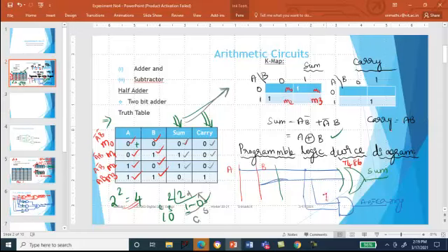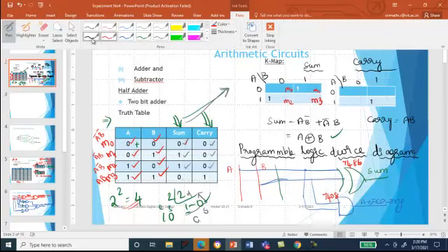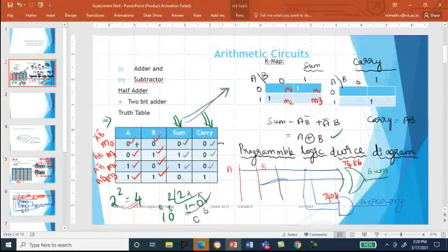So this can be implemented by using the IC 7408. Okay, 7408. And look at the transitions here. What is the transition? For each transition, in the sense of each combination of input going from one input to another, always try to make it 1 millisecond, such that each transition happens within a millisecond. Okay, assume like that.